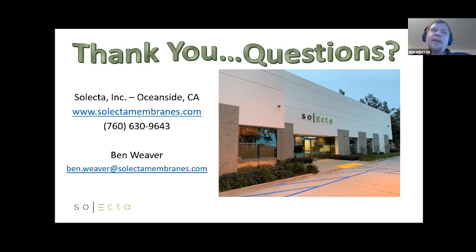At the end of life, you kind of hear stories about people flipping the element over and getting a little bit more life out of it. It can be done. I think it's probably more effort than it's worth. In actual practice, it's not going to recover drastically when you flip it over. But I have seen people extend life for a couple of weeks out of that.